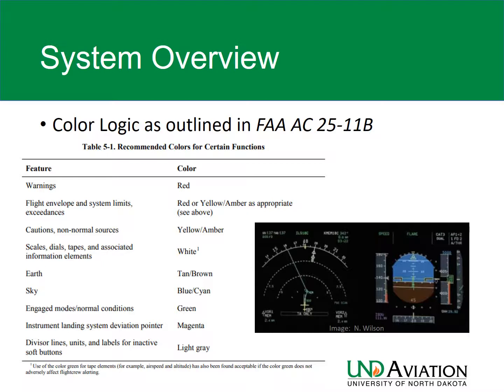Oh, well, very briefly, I wanted to talk about color logic. One of the ideas of the color logic on our screens is that when we move from aircraft to aircraft, there should be some semblance of intuitive transfer of how we process this information coming from our displays. And so there's actually a guideline. FAA Advisory Circular 25-11 has this information.